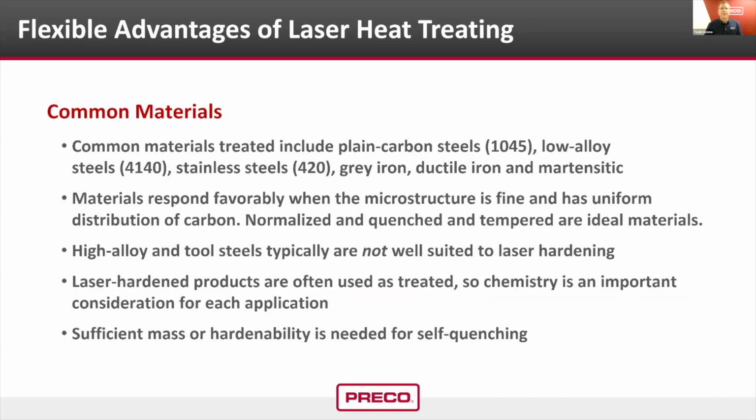The flexibility of materials that can be heat treated by the laser is listed above. This is just a small list that we have put together. These are the common materials that we see and also heat treat in our facility. The key takeaway here is carbon content and mass for self-quenching, so that liquids are not needed to cool the part.